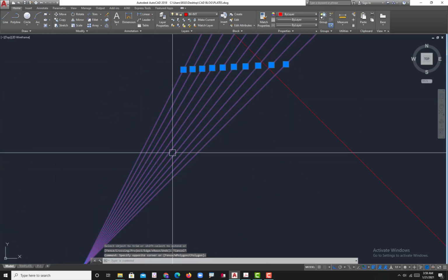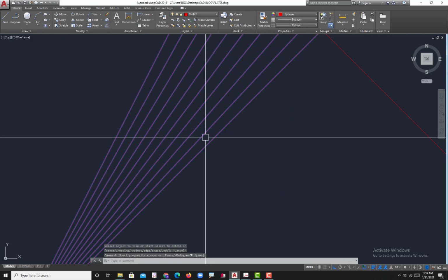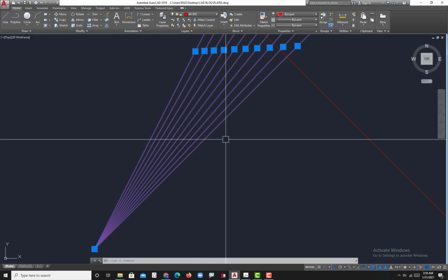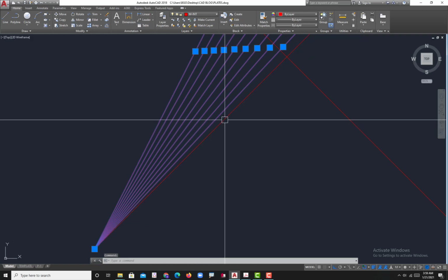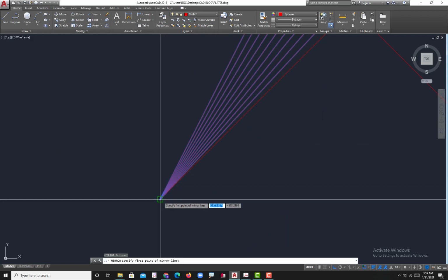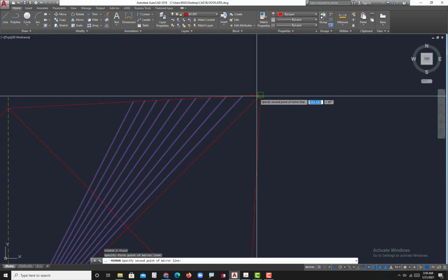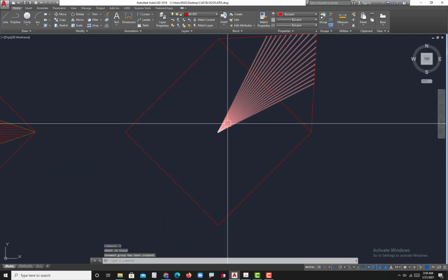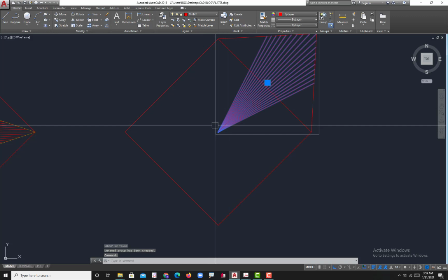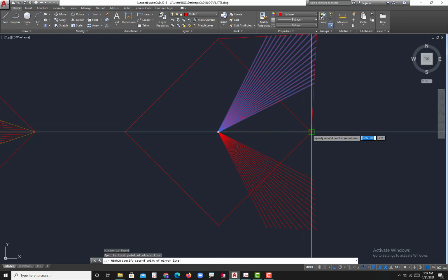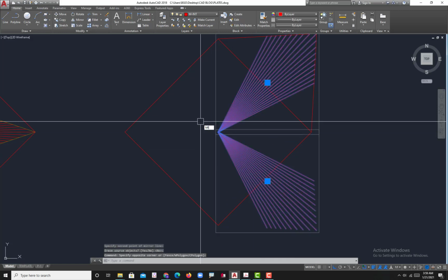Okay, so select, and then to deselect this one, if I selected these objects already, you just hit shift on your keyboard, then select this object here, and then MI for mirror. Select the intersection, and then you go there. Okay, and then let's say you group this one, select, and then mirror. Okay, get that one, and then you go to the horizontal, no, select the object, MI,